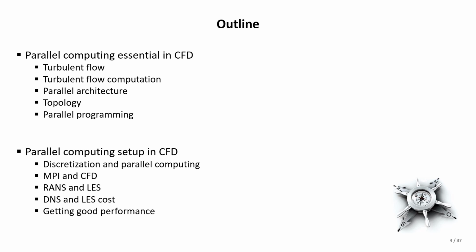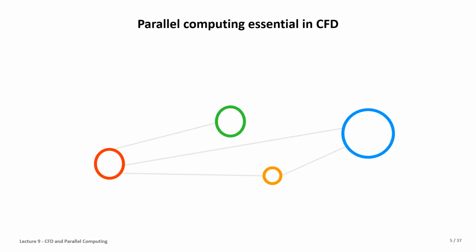We will have some examples regarding CFD methods in turbulent flow: RANS, LES, and DNS. We will compare their cost and their performance to help us choose the method according to the problem, and also about the HPC resources to solve the problem. So let's start the first part.